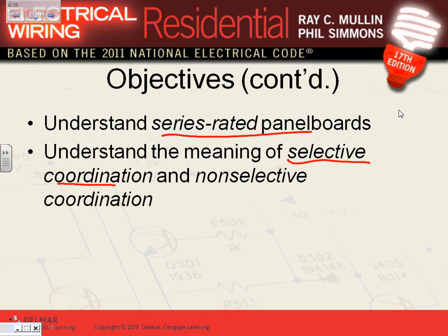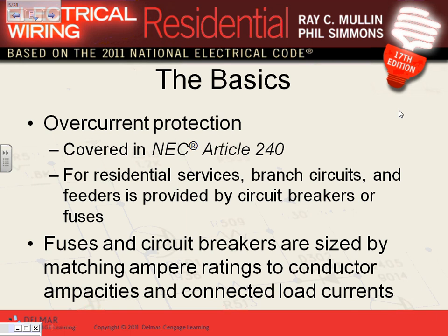Selective coordination and non-selective coordination. Anybody know what a selective coordination is? We talked about this one before. What's a selective coordination? Only the breaker affected by the overload. Thank you. The breaker that's affected by the short circuit or the overload will trip before the mains trip. That's a selective coordination. If you don't know it, I guarantee you as we move forward, guys, you're going to be doing coordination, using software to do all the coordination and setup for all these relays and circuit breakers. So it's coming. These are a few concepts in this chapter that I thought would prep you for what's coming in the commercial industrial.